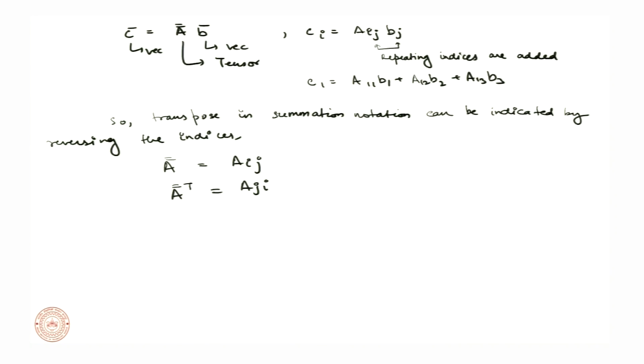I'll give you one example before we go into tensors. For example, we did this tensor rotation using a matrix, if you remember from the earlier case, in which A prime was equal to sigma A sigma transpose. How did we write this? So A prime ij will be equal to sigma ik akl sigma jl.